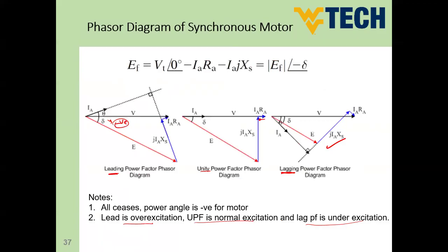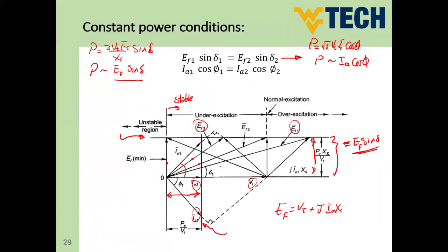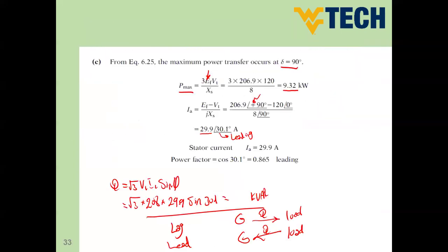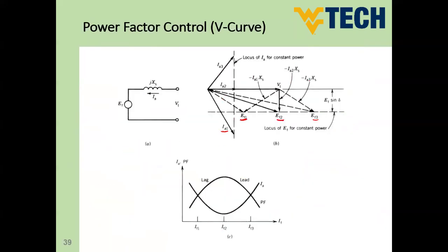If we go back a few slides to show you that again, here, this was the constant power operation that we discussed previously in our class. So we just mirror the phasor diagram across VT because we just convert the current. We just oppose the current direction. So this is why it's like a mirror across VT.